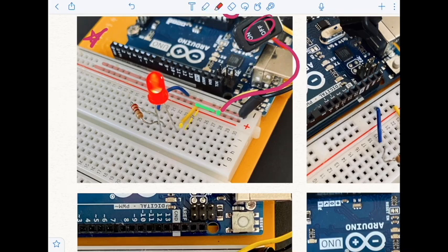Now since these ones are connected semi-horizontally in this case, if we call these vertical, these will be horizontal. They're connected like so, and so it'll flow from the edge of the wire to the LED, and from there it'll flow up the LED, do its thing up here, and flow back down. Now it's back on the breadboard, and it'll flow to this resistor here, and then get to the end of this resistor, which by the way just limits the amount of current that can run through the circuit so that it doesn't blow up under any circumstances.